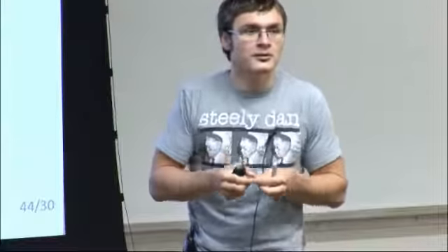Similarly, as for the other thing, and of course, the most mundane idea that we have is to increase the number of microphones. Okay, so nowadays, Przybyla, in one of the papers that I've shown in one of the first slides, uses something called capacitive micro-machined transducers. For example, they fit 37 microphones on a PCB 6.5 by 6.5 millimeters. It's quite fascinating. The problem currently is that they work at slightly higher frequencies, so their range is limited. But I think in the very foreseeable future, this is going to be the technology of choice for ultrasonic imaging in air.